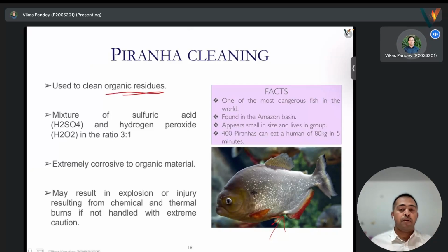When the wafer is coming, someone might have mishandled it a bit. And organic contaminants, although they are already there, the human itself is a big source of organic contaminant. So these things can be removed using piranha cleaning, the most commonly used cleaning process.